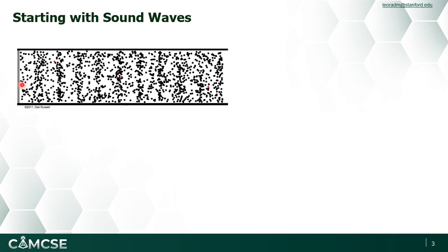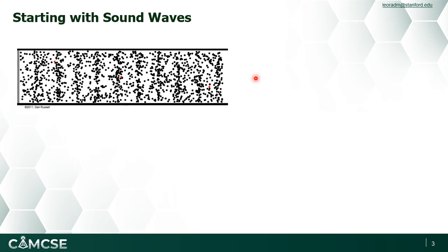If we have, say, a transducer like this gray material here, then as the transducer is vibrating at some characteristic frequency, it perturbs the atoms and particles that are near that transducer layer. This ultimately launches a wave of varying density that then transports and oscillates as it transports, carrying sound, or the timbre of the sound, based on the frequency at which the wave is propagating.